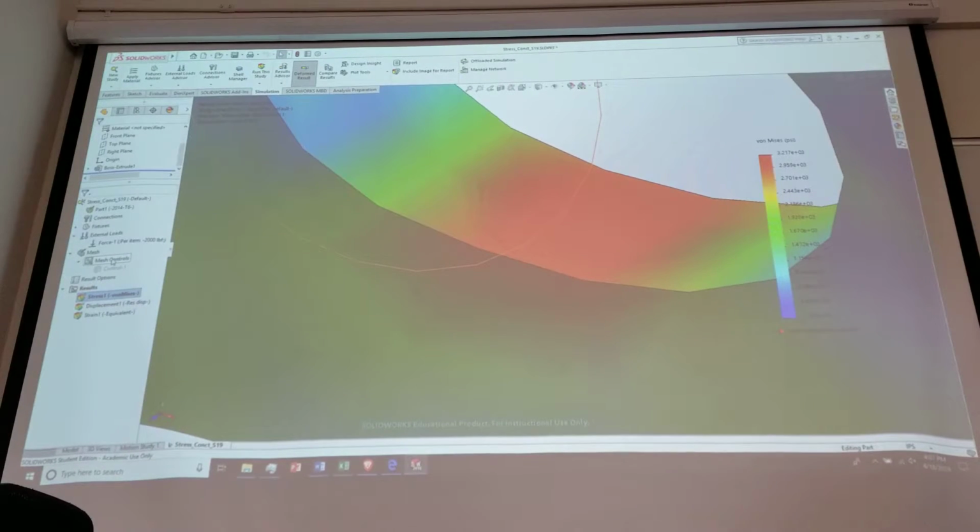Well, what do you think? Could we automate that? I'm guessing yes. We think we might be able to automate that. Because I think all we're doing is just changing the mesh density, right? And shoot, it's coming from the geometry. We're not changing the geometry. So maybe we could come up with an algorithm that would go in and automatically add mesh control and just remesh it and rerun the analysis until we got an answer that at least converged, or we ran out of time, depending on what we wanted to do. Okay.